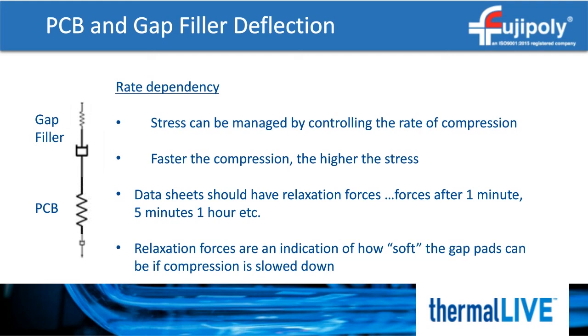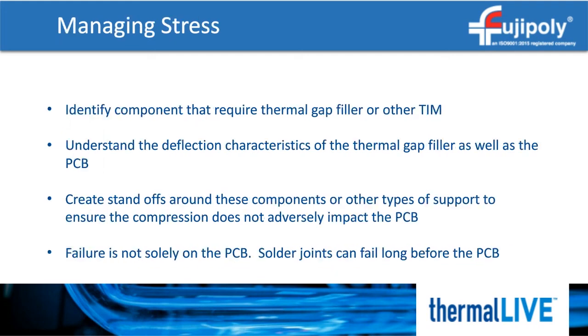Managing stress and strain is critical when using a thermal gap filler, especially gap fillers that are higher conductivity. This is due to the high level of loading that makes them less compliant. One of the best practices is to identify components early on in the design, preferably before the PCB is laid out. Once the board is populated, placing through-holes for support can be difficult or require big changes to the PCB layout.